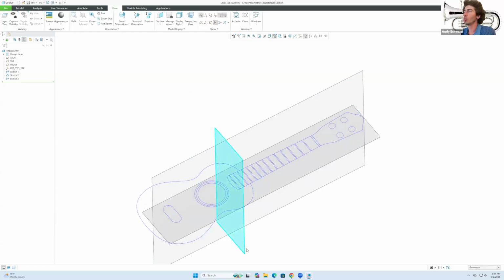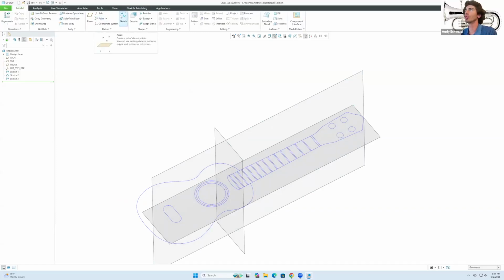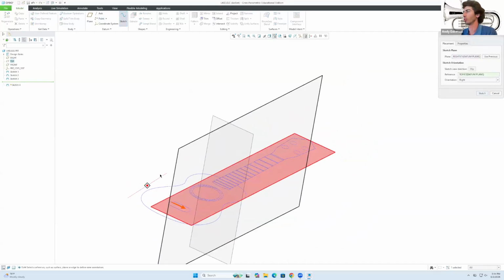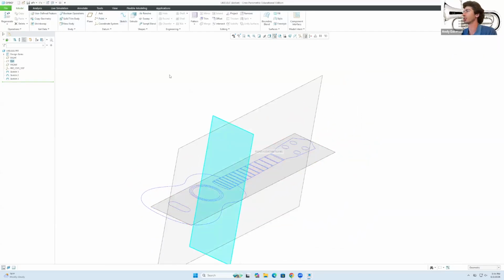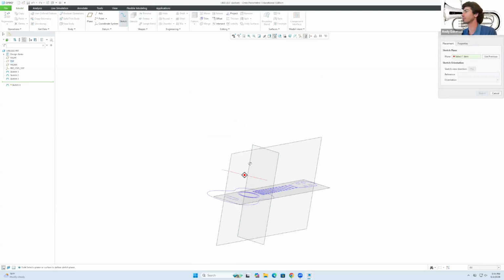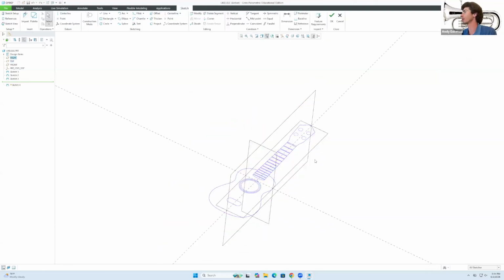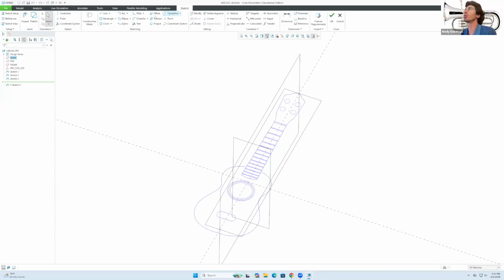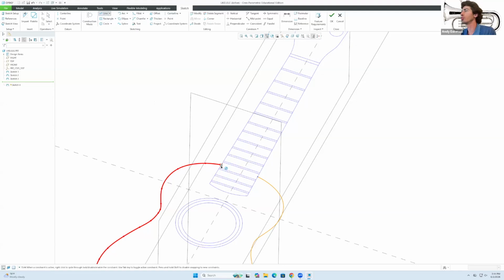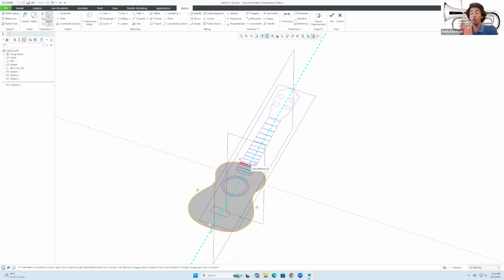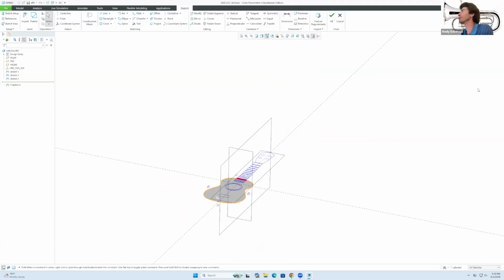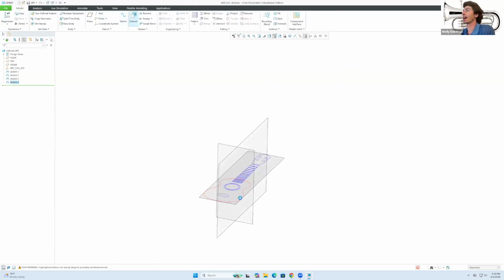Well, what you would need to do is go here to our friend model, and let's go to sketch. I know that's the wrong plane, cancel. Yes, go here to sketch. In here, I want to choose that plane there, sketch. So now what we can do is go to project. Where are you? In here, and I'm gonna select that line and that line and hit OK. And then I'm gonna connect these two using a center line. So that becomes shaded. So what we can do is now exit and give that some volume.